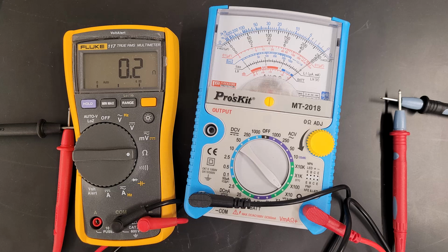The next question, when is an analog multimeter preferred to a digital multimeter? A lot of people don't use analog multimeters anymore, but if you're trying to adjust a circuit for maximum or minimum values, and there's any changes that are happening, on a digital multimeter the values are constantly changing. You'll see those digits changing, and it can be difficult to see exactly what the value is. So if you're adjusting just for maximum or minimum values, you can use an analog multimeter, and the needle will stay low and maybe bounce a little, but you can see what that real low value is.